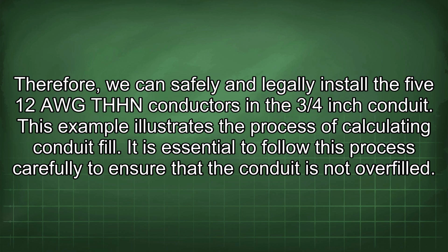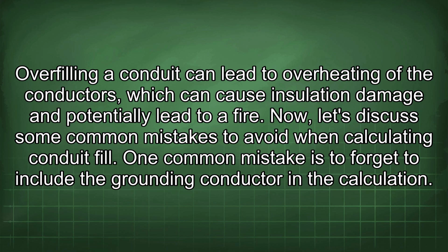This example illustrates the process of calculating conduit fill. It is essential to follow this process carefully to ensure that the conduit is not overfilled. Overfilling a conduit can lead to overheating of the conductors, which can cause insulation damage and potentially lead to a fire. Now, let's discuss some common mistakes to avoid when calculating conduit fill.